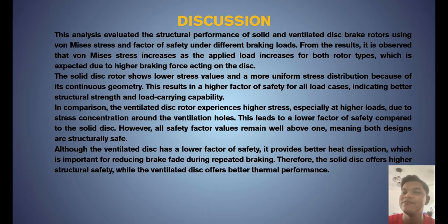So we continue with the discussion. This analysis evaluated the structural performance of solid and ventilated discs using von Mises stress and factor of safety under different braking loads. From the results, it is observed that von Mises stress increases as the applied load increases for both rotor types, which is expected due to higher braking force acting on the disc. The solid disc rotor shows lower stress values and more uniform stress distribution because of its continuous geometry.